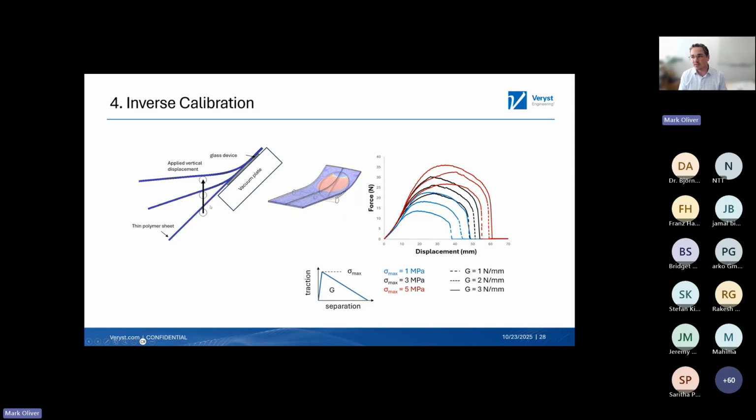So from a material property point of view, this is a terrible test. But if you're doing a finite element analysis of your test anyway, then all these complexities are okay because you're going to simulate it anyway. So the fact that your bond length, the width of your bond, varies as you move around this circle, and the angle of loading changes, doesn't really matter.